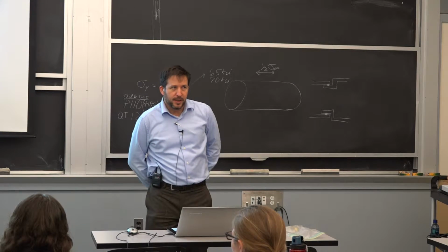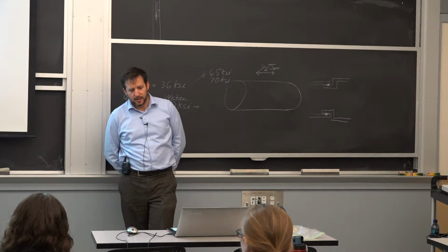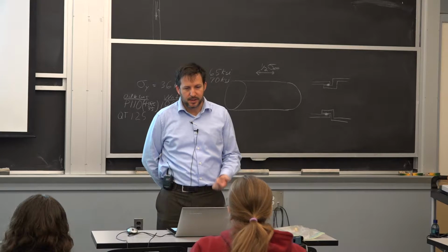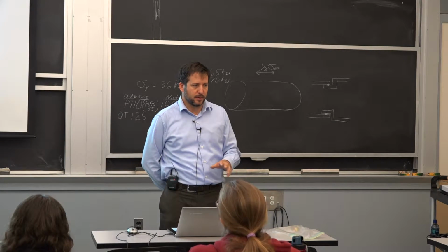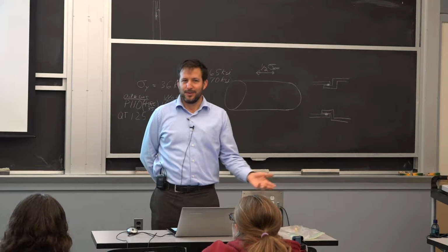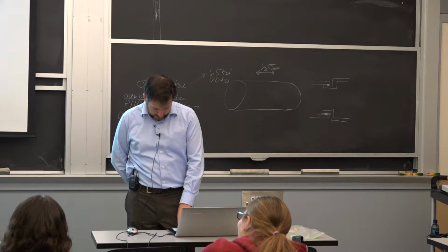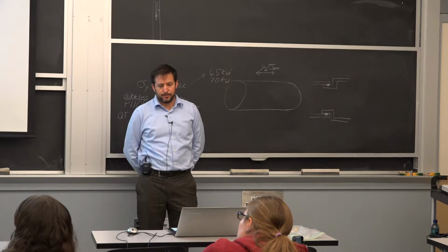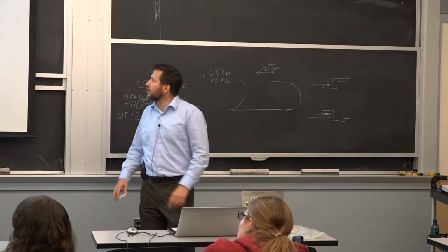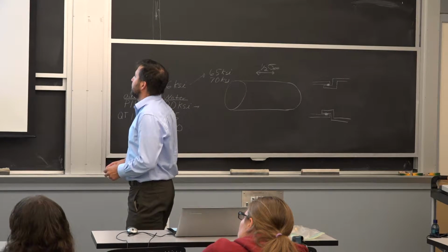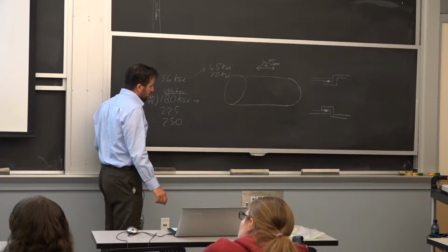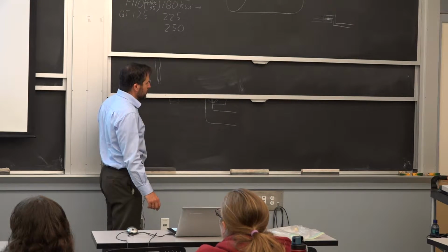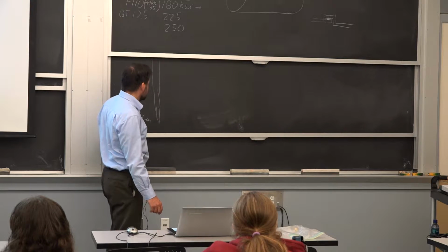We'll go to fusion welding, just get started here, and I want you to keep in mind the main reason we're doing this is manufacturing, overall cost of fabrication. If it wasn't for that, we would probably avoid it altogether. The very traditional welding, also called stick welding or shielded metal arc welding, essentially uses an electrical arc to eat both the consumable and the base metal.